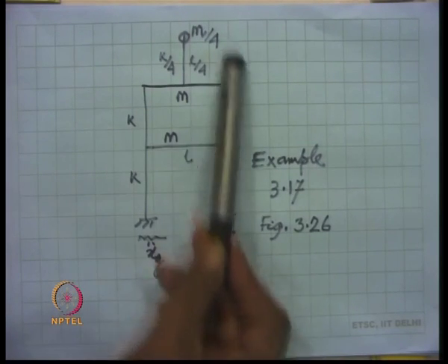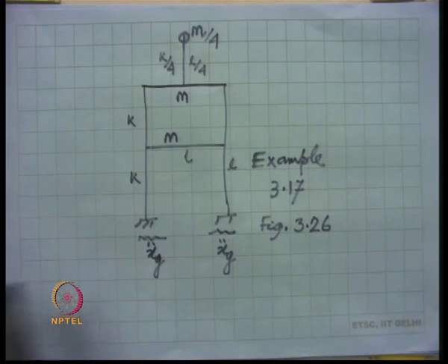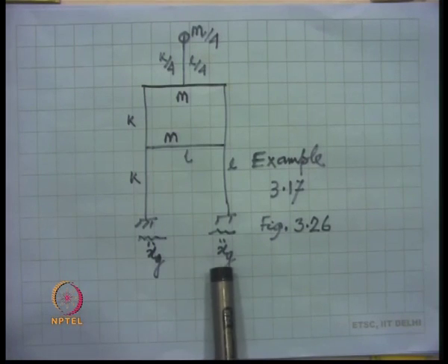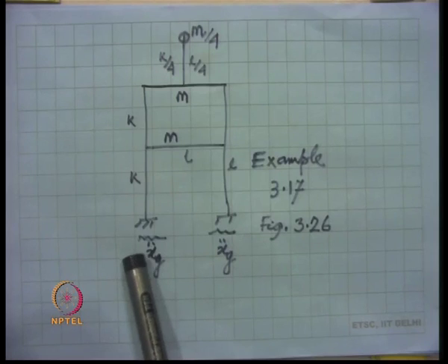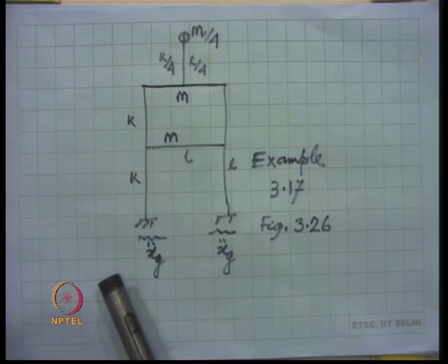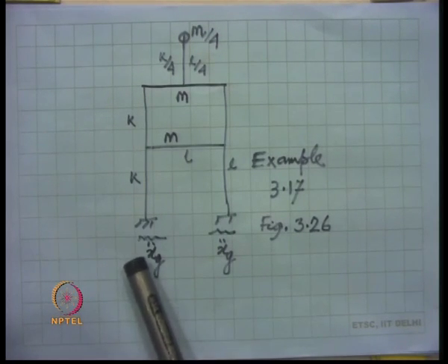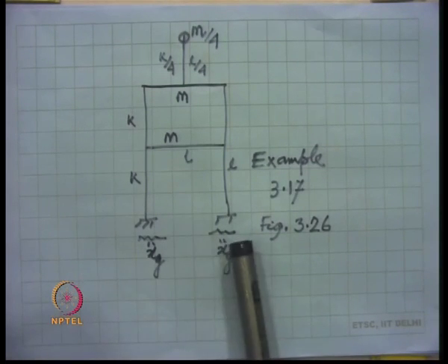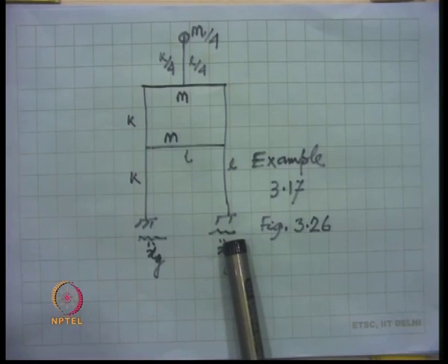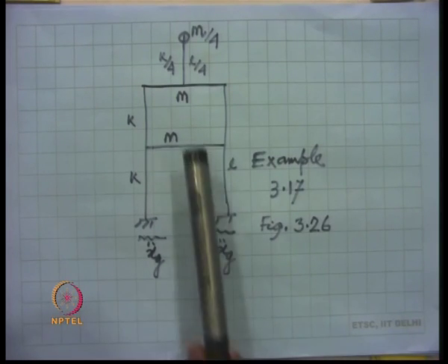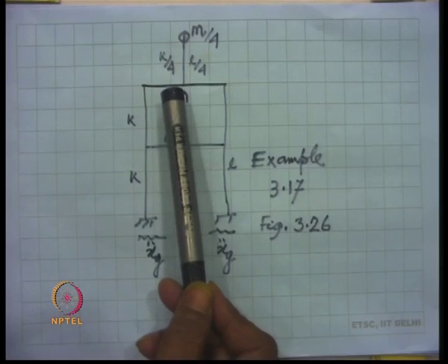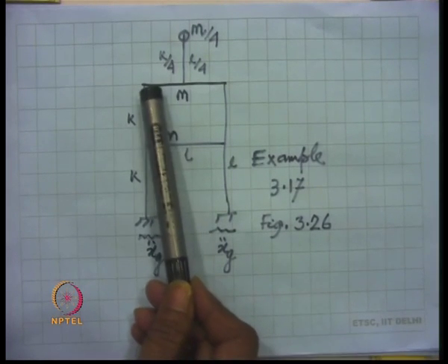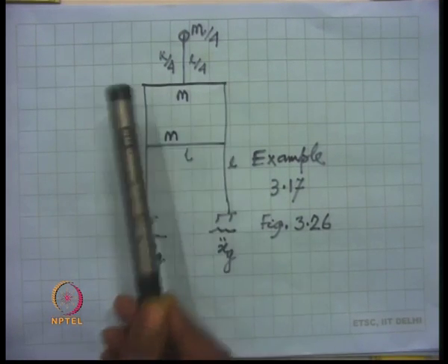Now, for this system, for the specified ground acceleration, here the specified ground acceleration is taken as the El Centro ground excitation. We perform a time history analysis. We can perform the time history analysis either in the time domain or in the frequency domain, and find out the time history of the absolute acceleration for the top floor level.